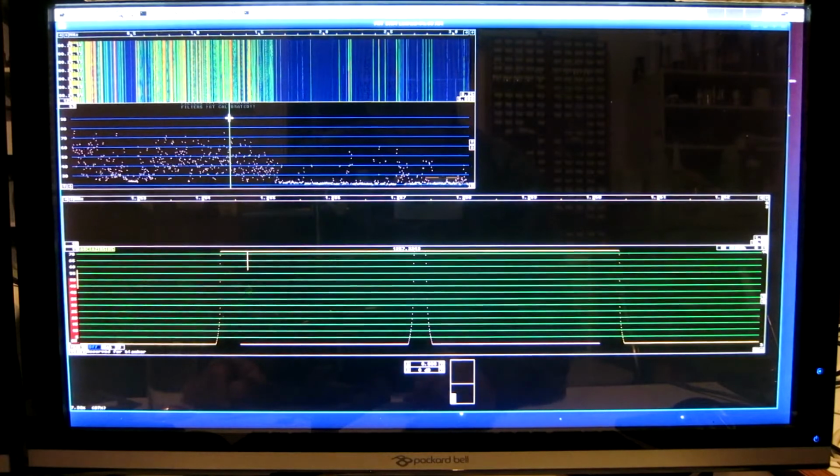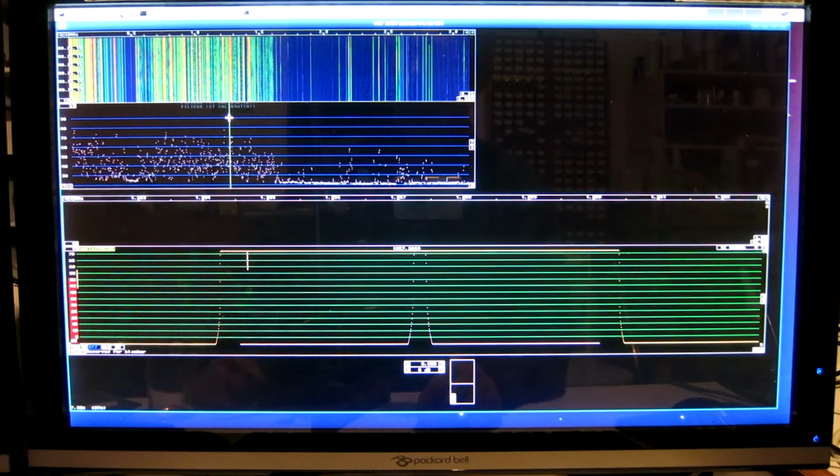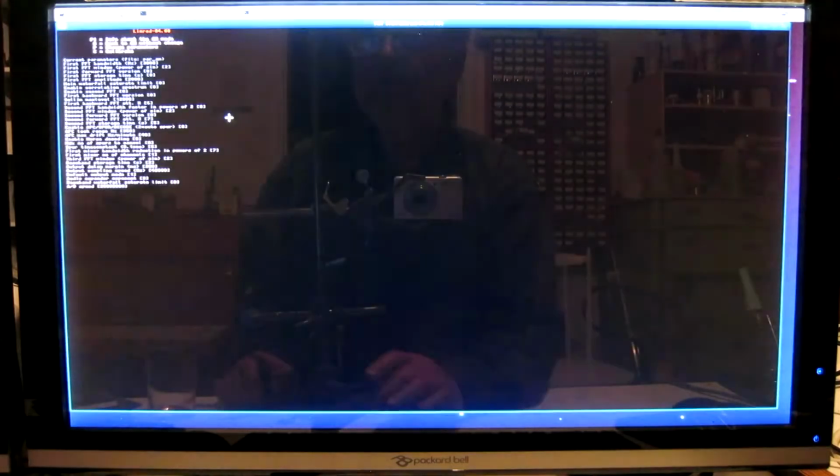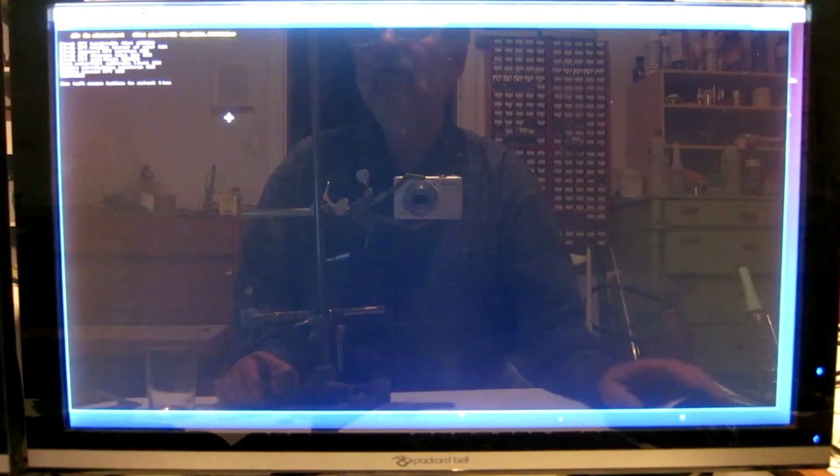The CPU load says 87%, but that's not a safe indication that things work properly. When there isn't time to do something, the computer will get idle rather than working on something that it knows it cannot do in time.